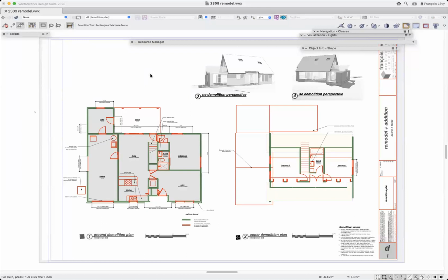What's nice about that is, for the sake of simplicity, you don't overburden yourself with extraneous classes and subsets. And also, in this case, you'd utilize data visualization, but set your criteria for records, objects using record, and it could be a construction phasing record. You can utilize data manager to help facilitate that with an existing document, if you're wanting to transition to that methodology. Data manager is probably something you want to learn more about.